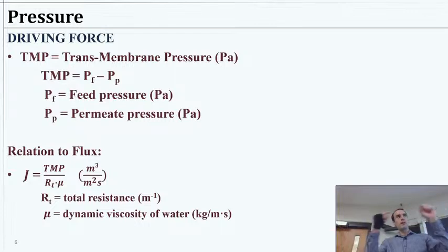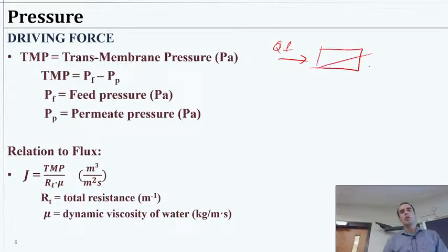Can we measure it right inside the membrane itself and all that? But for our purposes, we're just looking at if we pressurize a feed and we're comparing that to what happens to the pressure drop across that membrane, where we have some pressure in the permeate different than the pressure in the feed.